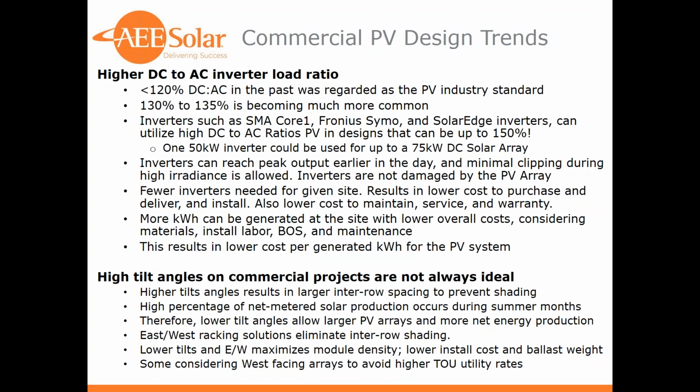Calculators like HelioScope and PVsyst could be used to calculate the amount of power that can be lost to clipping, and also calculate the value of facing arrays west or south. And then you can choose your inverter capacity and your tilt and orientation to maximize your value to your customer.